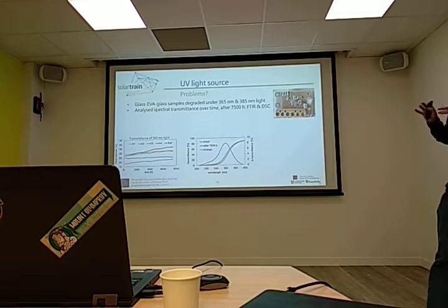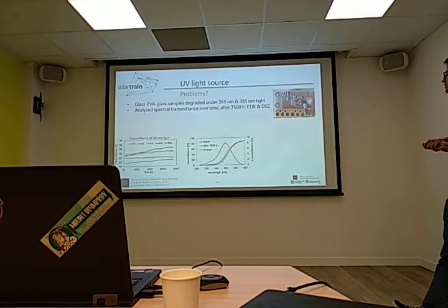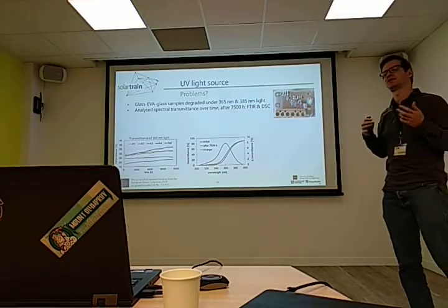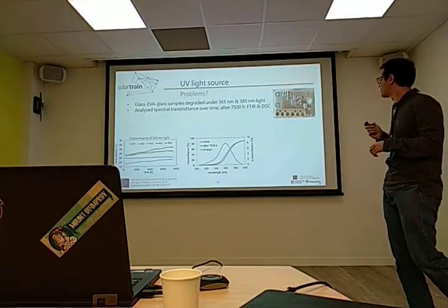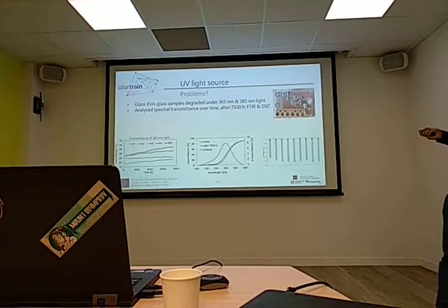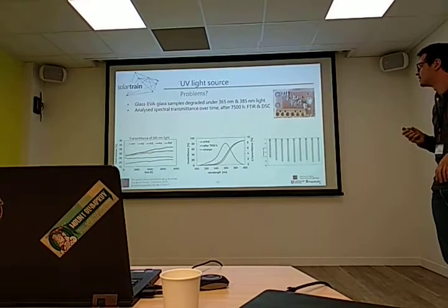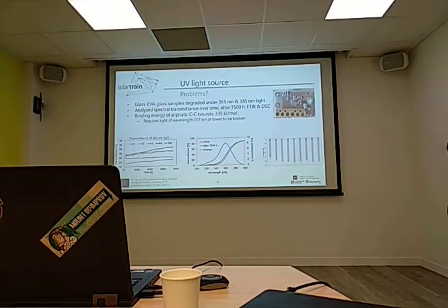And we saw some changes in the transmittance of UV light, so there were some changes in the material: over time, under the 365 nanometer light, the samples got more and more transmittent. However, the other analysis didn't yield any conclusive results, so there were no chemical changes in the encapsulant itself. This wasn't very surprising, at least not to the guys who knew something about it.